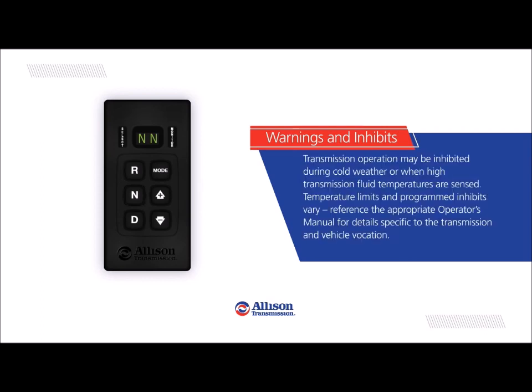Transmission operation may be inhibited during cold weather or when high transmission fluid temperatures are sensed. Temperature limits and programmed inhibits vary. Reference the appropriate operator's manual for details specific to the transmission and vehicle vocation.